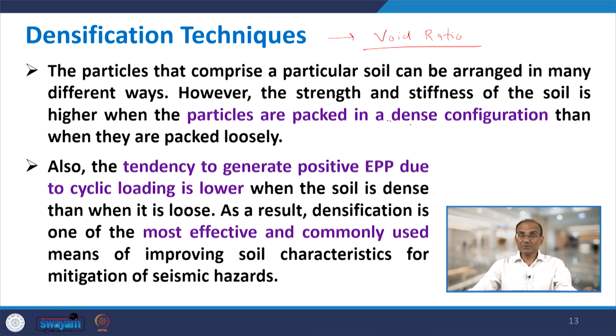So, if you reduce the voids by densification, then you are going to increase strength and stiffness of the soil. Also, the tendency to generate positive excess pore pressure due to cyclic loading is lower when the soil is dense than when it is loose. This we already discussed when we discussed liquefaction. As a result, densification is one of the most effective and commonly used means of improving soil characteristics for mitigation of seismic hazards.